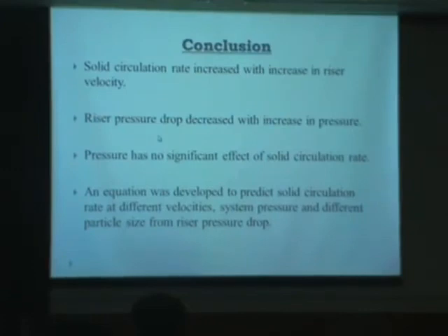Solid circulation rate increases with increase in riser velocity, and riser pressure drop decreases with increase in pressure. Pressure has no significant effect on solid circulation rate, and an equation was developed to predict solid circulation rate at different velocities, system pressures, and different particle sizes from riser pressure drop.